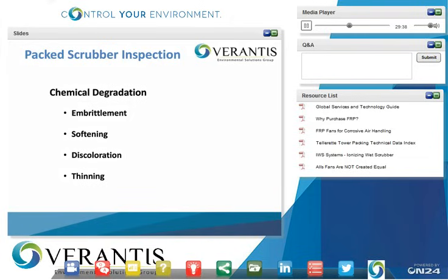Discoloration can occur for a lot of reasons, and it's usually the first indication of some type of problem. If the discoloration is not due to an actual buildup of material on the packing, then it's a good first indicator that there is some level of chemical degradation occurring inside the unit, even if no other symptoms are being observed. And then the last is thinning or dissolving. Again, there are certain organics that can cause this, aromatics such as toluene, and also very reactive gases such as fluorine gas, not hydrogen fluoride, but fluorine gas itself, F2, which can cause this kind of problem.